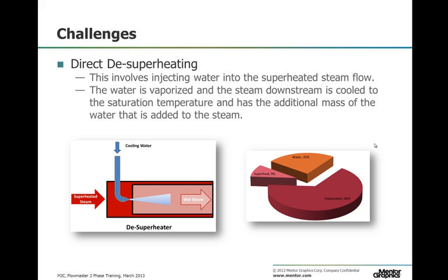The downside of superheated steam is that the usable energy in the superheat is quite small compared to the enthalpy of evaporation. The diagram on the right shows the typical enthalpy split of superheated steam. Additionally, the heat transfer coefficient of superheated steam is much lower than that of saturated steam and can be variable and difficult to predict. This causes an issue with the ability to properly size components for particular systems. If superheated steam is used as a heating source, it is typically also required to have a larger and more expensive heat exchanger than a wet steam system.